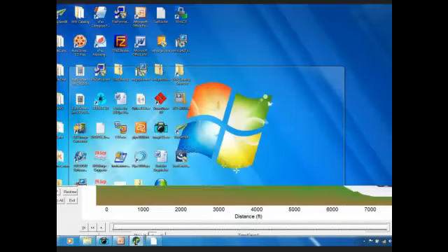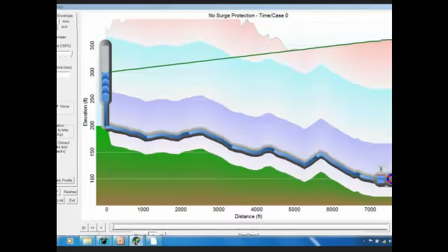Now, here's one of the animations, and what's going to happen here is this is just showing the pump. Here's a check valve, and then it's pumping up this pipeline. It's sort of animating the flow. When we trip the pump, you'll see the pressure drop very quickly, the check valve close, and you'll see what happens in this system.